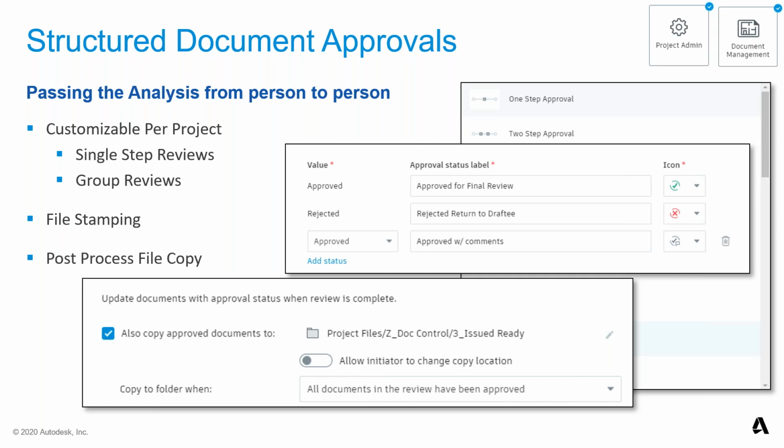Again, the model coordination space as a whole has got a lot of functionality and features inside there. And if you want to dig into that, you can absolutely do that at some point. However, the simple process for a Plant 3D project is we can create a very simple workflow that if you want to go through a digital approval of a model, you can automate the copying of that model into a coordination space, which will also then automatically check for clashes against a Revit file or a 3D file or whatever other IFC files are in there. And issues and that sort of issue management can be dealt with in an entire project space in BIM 360.